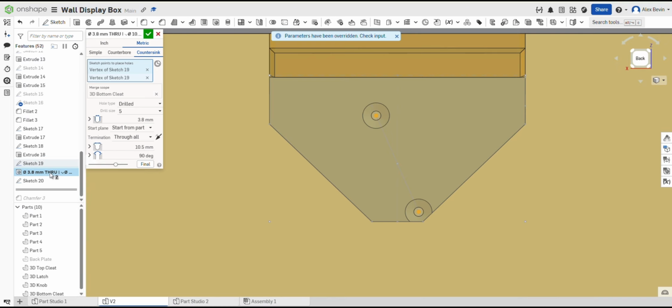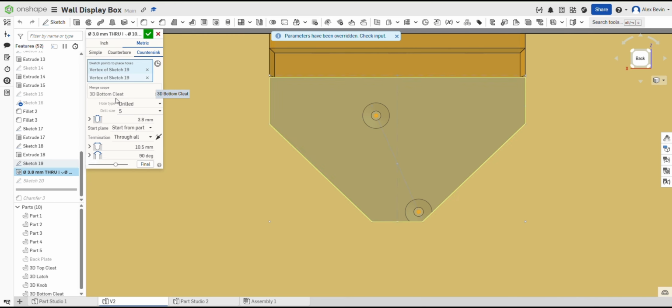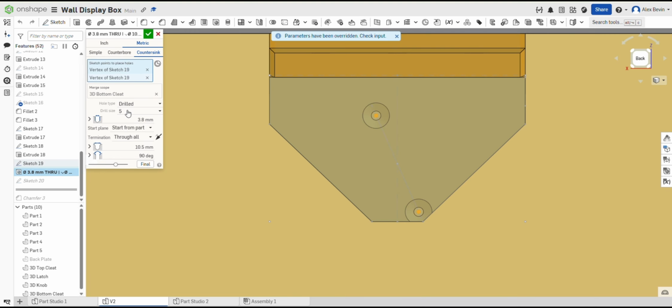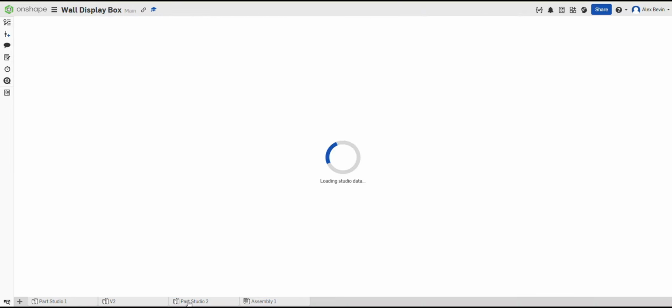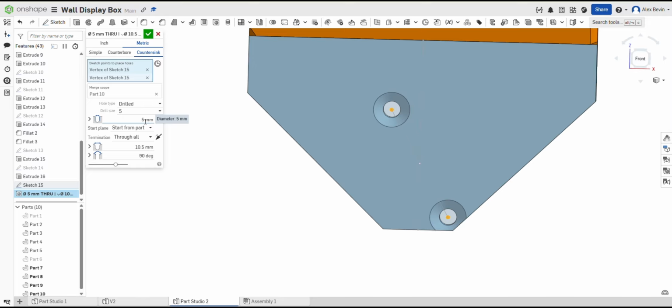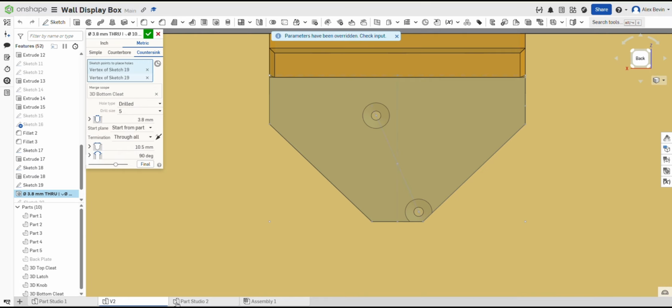Does it still sit flush and does it clear? Before we move on, quick quality check. Turn section view on and off and confirm two things. 1. There's no clash. 2. Nothing we've added stops the part sitting flat to the wall. If it doesn't sit flat, it's usually because you chamfered a wall contact edge by accident. Just roll back, fix the selection, and carry on.